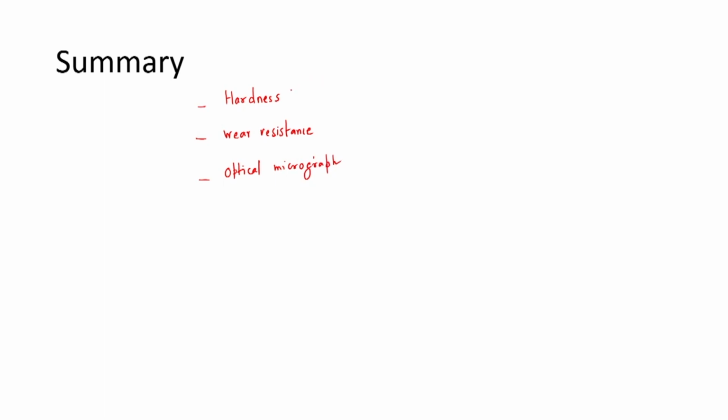We have seen that hardness is increasing in laser treated samples. The wear resistance is also found to be increased during laser surface processing. Optical micrographs have given us the idea about the hardened depth. Overall, we can say that lasers are quite useful to enhance the hardness value and the wear resistance value during laser based material processing.